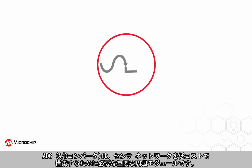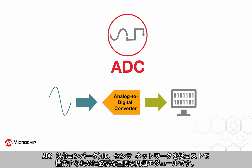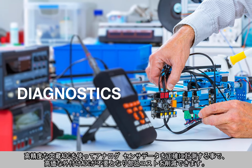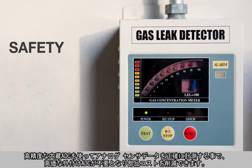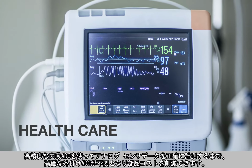An analog-to-digital converter, or ADC in short, is one of the critical peripherals required to build cost-effective connected sensor networks. An accurate, on-chip ADC can save BOM cost by offering precise measurement of analog sensor data without the need to include an expensive external ADC to your design.